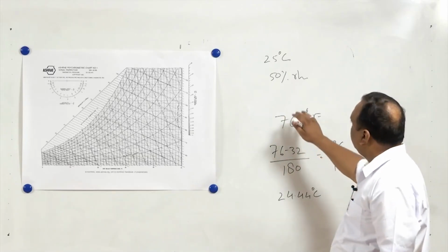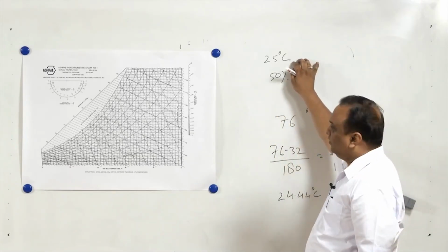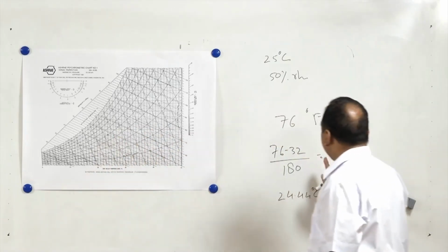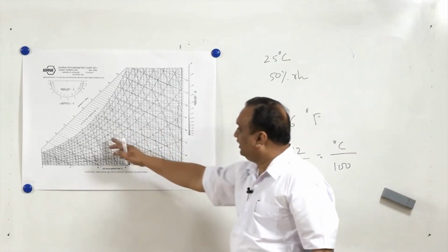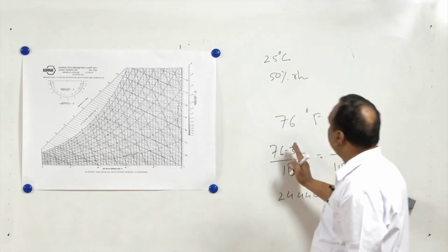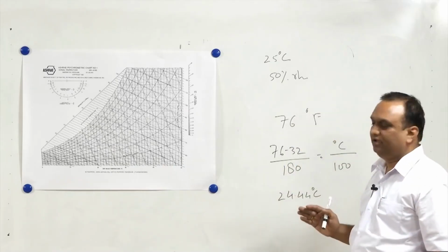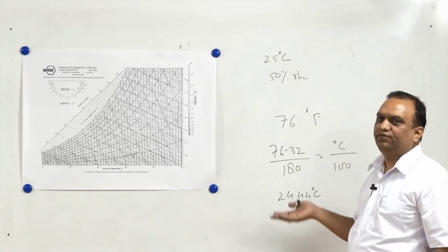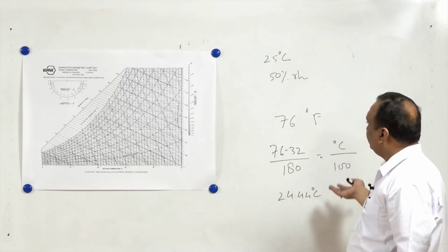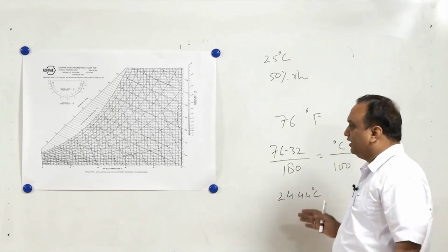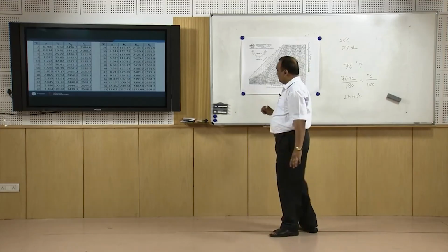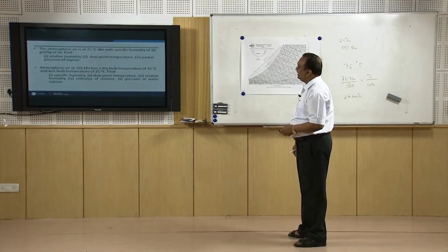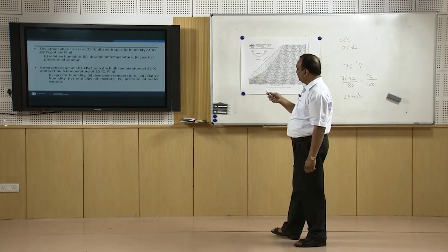but we take 25 degrees centigrade because in India most of the time we are doing cooling. So we do not recommend cooling up to 24 degrees centigrade. We say if you cool up to 25 degrees centigrade, the ideal state is attained. This can save some energy also, and at 25 degrees centigrade temperature, most of the people in our country feel comfortable. Now after this, we will take some examples. I think that will make things clearer here.